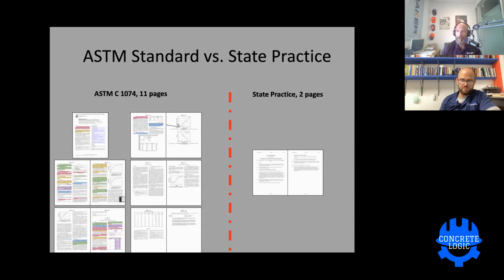Okay. Well, if you could at some point you can address it now, but this one item that I saw a couple times in the ASTM, it says the method does not take into account the effects of early age concrete temperature on the long-term strength. And there's things you have to do to adjust for that. Right. So early age temperatures impact on later strengths.